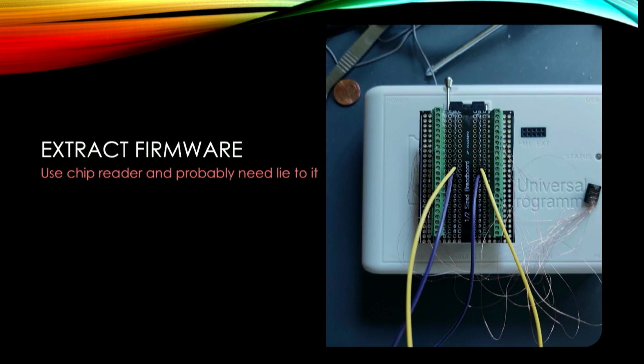If it is wrong, and you know the data of this flash memory matches what you're looking for, like the voltage and all that type of stuff, just tell the chip reader to ignore the actual chip ID, and it'll still read all the data out of it clean. And I've done this with dozens of different chips many times. On these particular chips, I haven't run into this, but I've run into certain weird BGA chips where I was able to do this same attack on those.